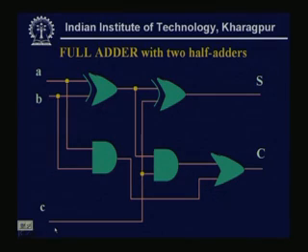So, if we want to summarize, using these two types of adders that we have shown, for each type of adder, half adder and full adder, a number of different realizations are possible. Depending on the application, whether we want to reduce the area or the power, we will select that realization consisting of AND OR gates, XOR gates or NOT gates, etc. Okay.